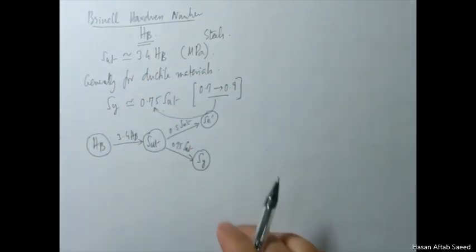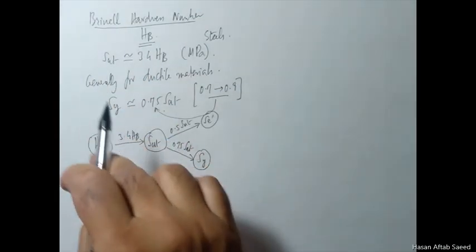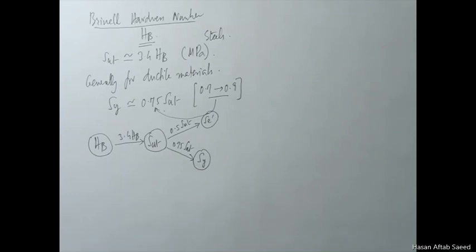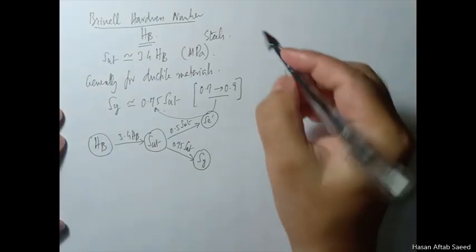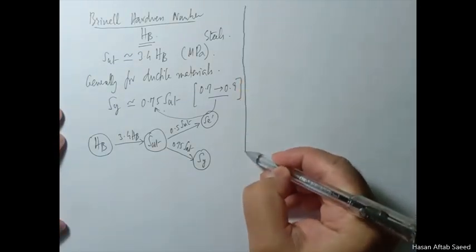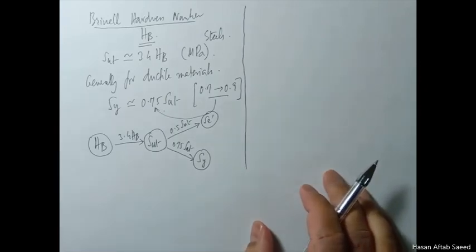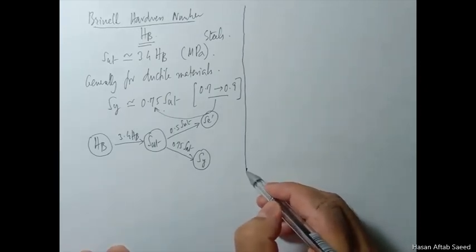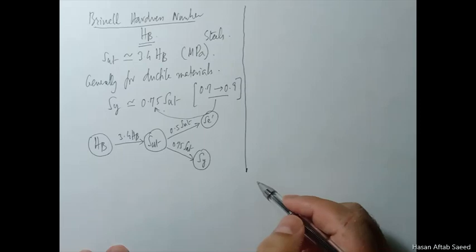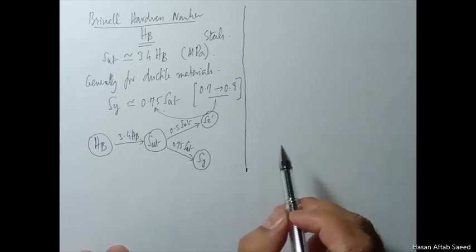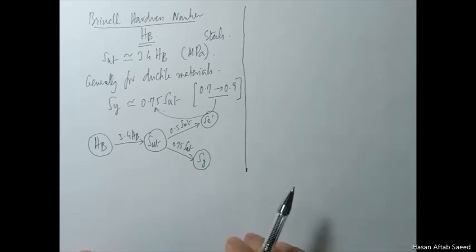So from one hardness number, you know so much about a material. Obviously, there is a range, and there will be some error. It's not very accurate, but it's reasonably accurate. I mentioned this because in some of your questions at the back of the book, the question only gives you Brinell hardness number and then wants you to do some calculation. So this will come in handy.